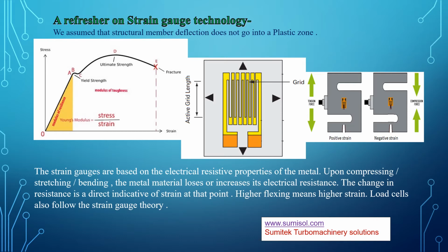Normally in the field of sensor electronics, the Wheatstone bridge setup is the preferred method. It can be a quarter, half or full setup depending on the requirements to measure the deflection in the structural elements. The strain gauges work on the principle of Hooke's law, which then needs certain assumptions. In this case, we can assume that the base frame structure is linear in nature.